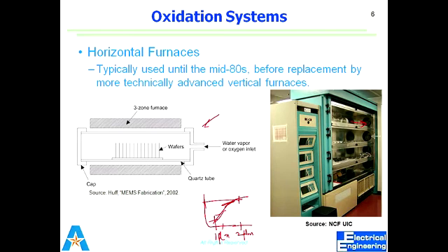The wafers are inside, and one thing that is missing here is that we have the exhaust as well with that tube, the furnace, the quartz tube, because the oxidant comes in at the same time. If there are some byproducts or even ambient oxygen, that needs to go outside as well. So there is an exhaust pipe as well.